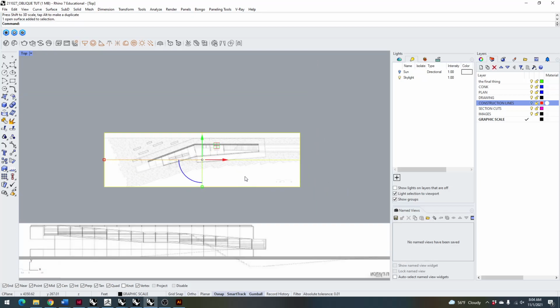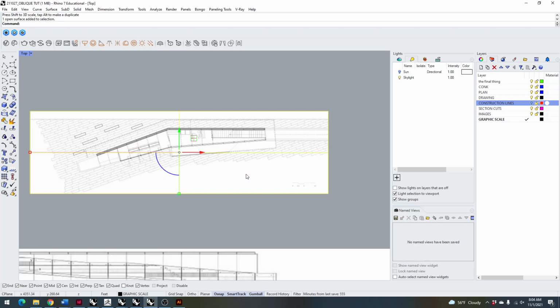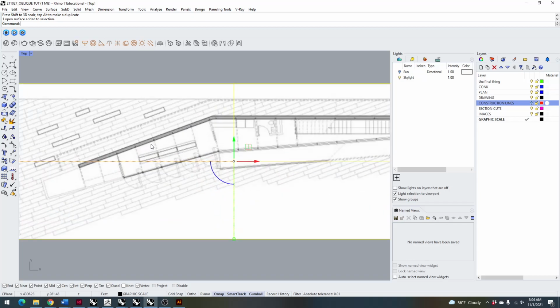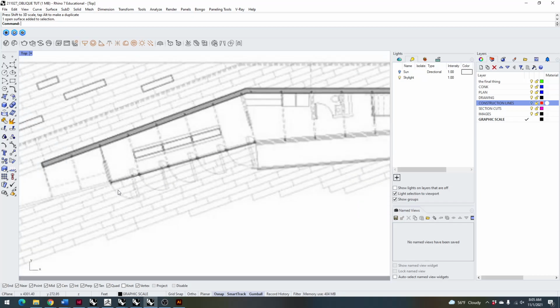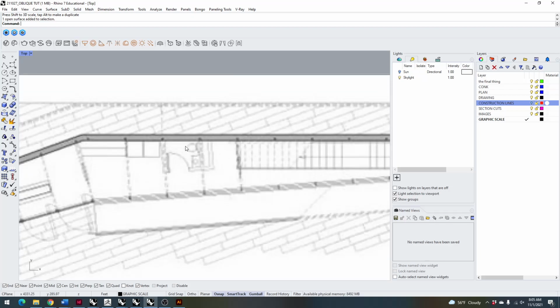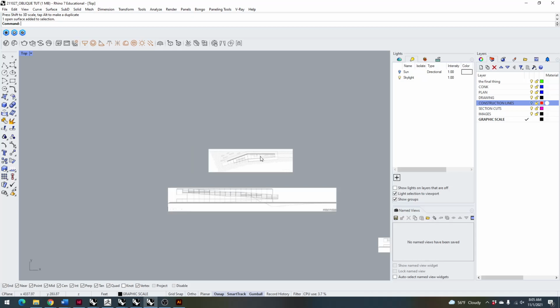So graphic scales are a great device if you want to know a scale when you're just arbitrarily printing a sheet, or arbitrarily printing drawings that other architects have done without knowing the scale that they were drawn at. And generally you can reference known dimensions such as doors, etc., to help you determine what those units are.